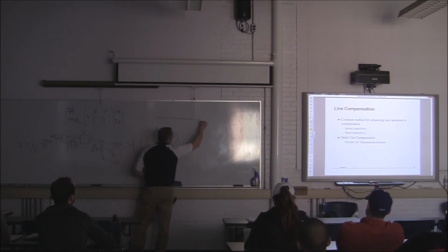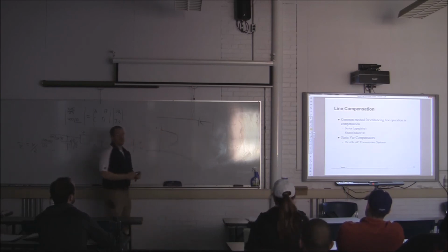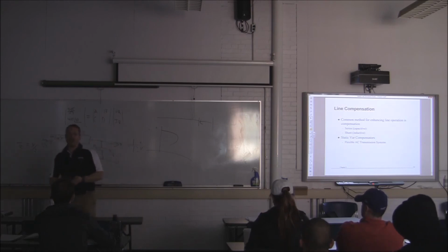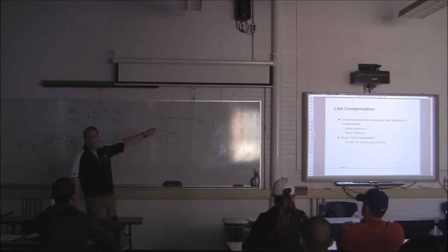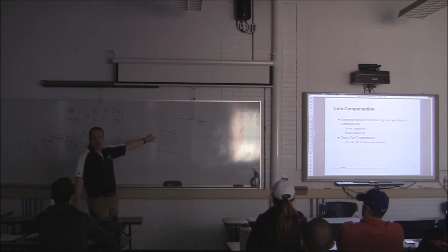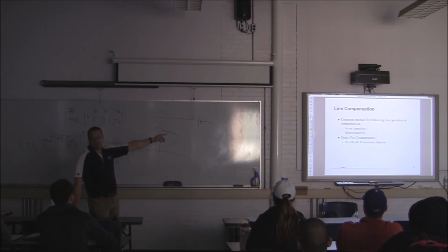what if I put a series cap in it? There used to be a series capacitor in Orrington, and its whole purpose in life was to reduce the value of Z seen by the transmission line. I don't think they use it much today, or if ever, but is that a series cap or is it a shunt? I don't know. But series capacitance actually helps improve the impedance of the line.